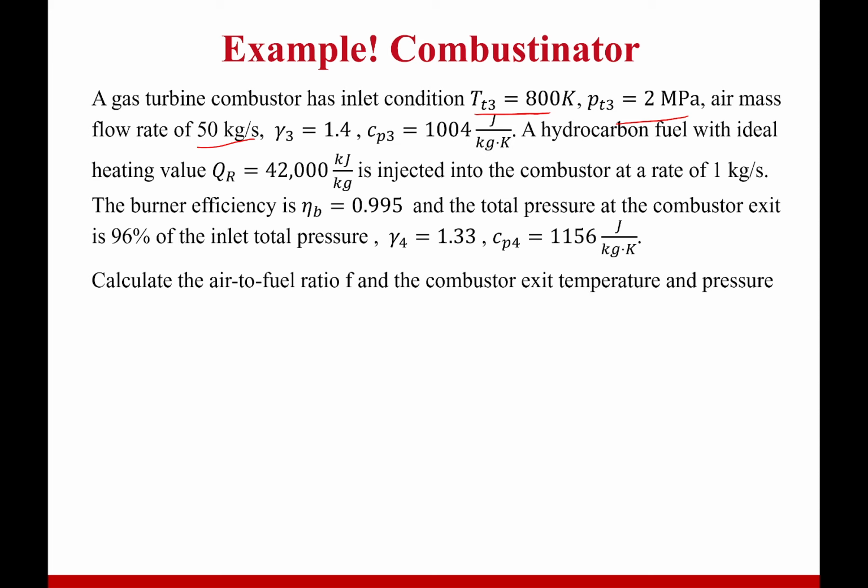Okay, so what are we burning? Well, it's a hydrocarbon fuel, so my heating value is 42,000 kilojoules per kilogram, and it's going in there at 1 kilogram per second. And my burner efficiency is pretty high, which is expected. So we have a whole lot of information here.